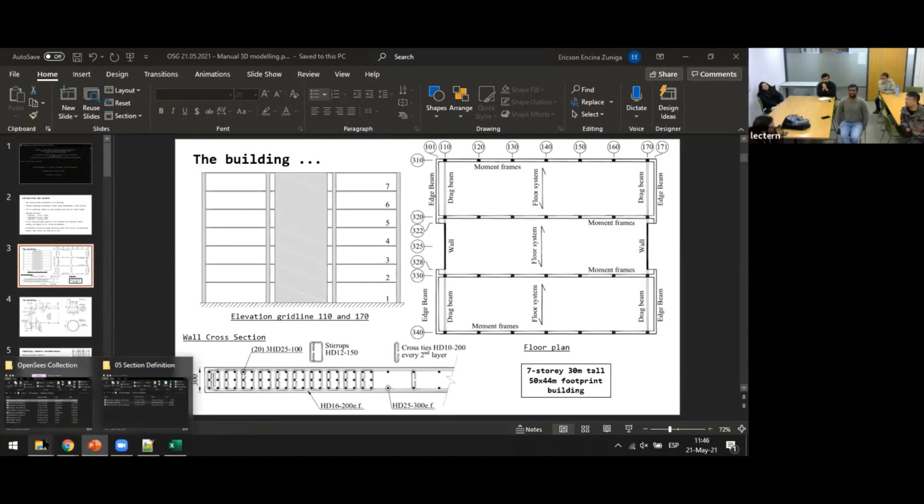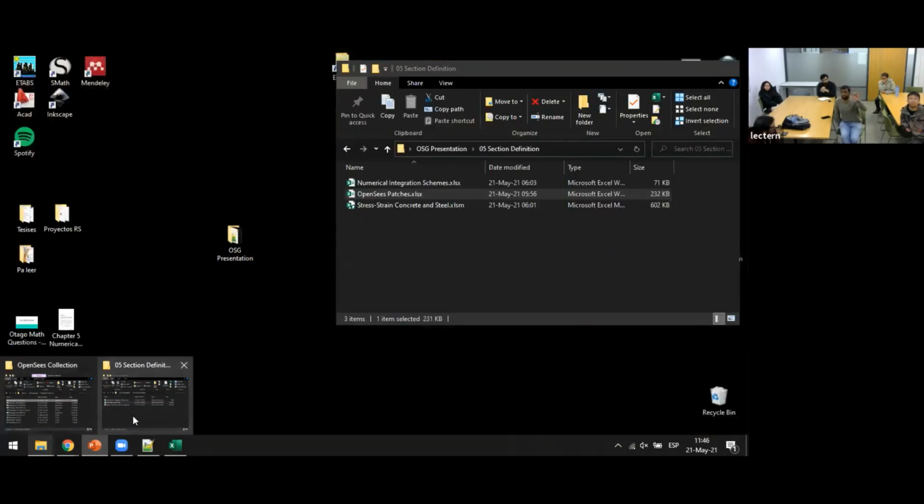For the fiber section, you can record the response at the particular fiber. If you're using OpenSeesPy, there is a set of commands. He is asking for the layer response. That can be done, I know for the fiber it can be done. I have the code to do that, but I don't know where it is.